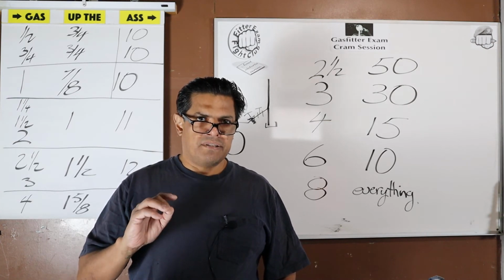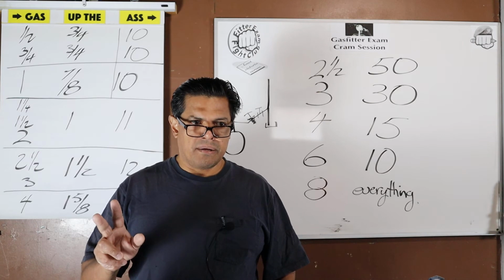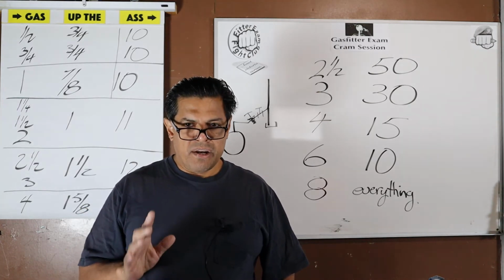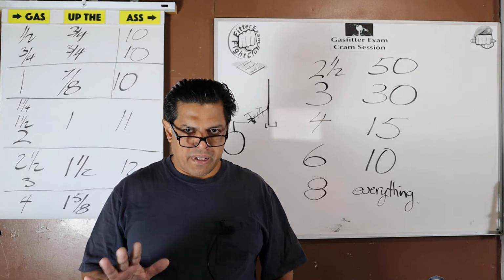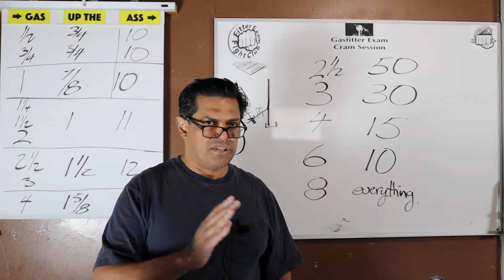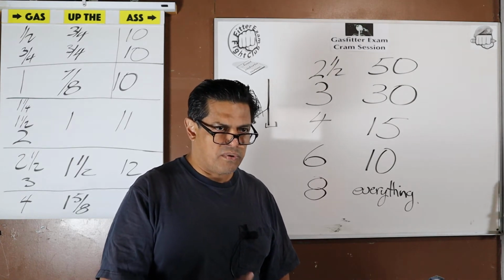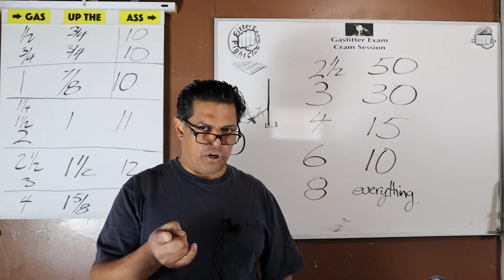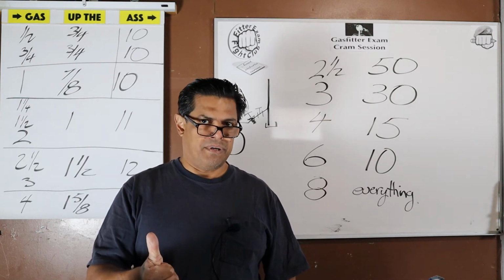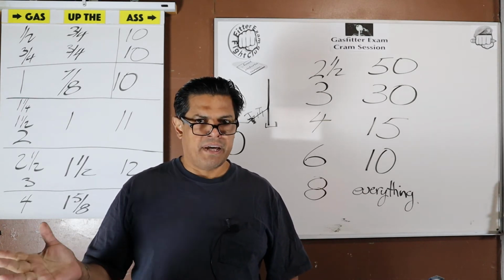And there are places where you can run it, but not if it's this or that. Okay? You can run gas piping in a plenum, because a plenum can be so many things. I know we just got done in the previous test where we're not going to run it through a return air plenum. We're not going to run it in a furnace plenum. But there are other plenums.